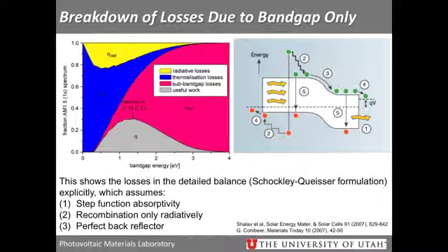So if you have a really low bandgap material, let's say 1 eV or less, there is an immense amount of light that you will absorb, right? Most of the spectrum is above that energy. But if you look at number 2 on this diagram here, you have a really high energy photon. Your electron is kicked way above the bottom of the conduction band. And if you know from quantum mechanics, electrons don't want to sit in a really high energy state. So particles will try and relax down to the lowest possible energy state, which for a photovoltaic is going to be the bottom of the conduction band.